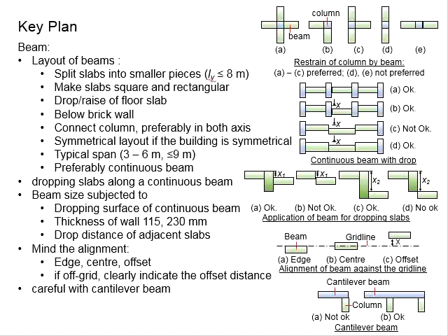Your typical span for the beam will be somewhere between 3 to 6 meters. Very seldom for the normal usage, I'm referring to the typical residential, office or commercial building, very seldom do we have a beam of more than 9 meters.